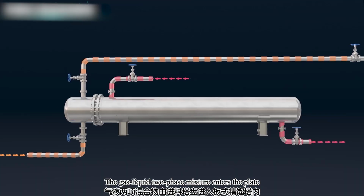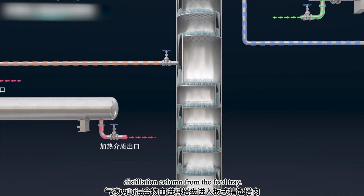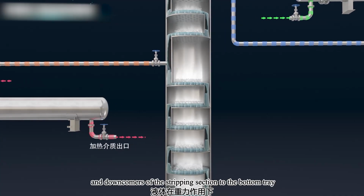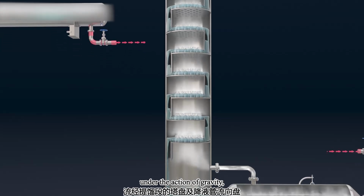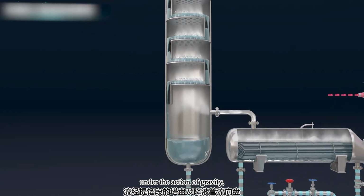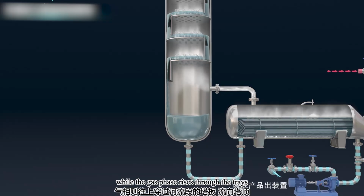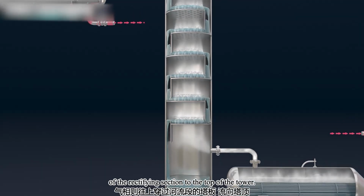The gas-liquid two-phase mixture enters the plate distillation column from the feed tray. The liquid flows through the trays and downcomers of the stripping section to the bottom tray, under the action of gravity, while the gas phase rises through the trays of the rectifying section to the top of the tower.